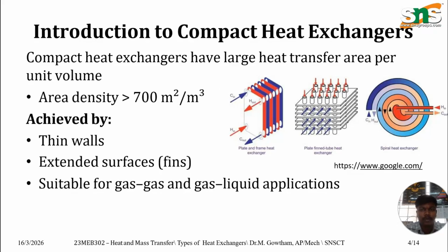So here is some introduction of the compact heat exchanger. It has a large heat transfer area per unit volume, which is the area density, achieved by thin walls and extended surface fins, and it is suitable for gas to gas and gas to liquid applications.